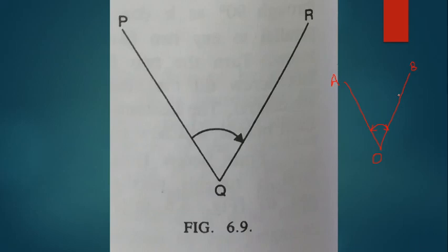Let us say it is approximately matching, then I can use the tangent screw or slow motion screw, that is the upper tangent screw or upper slow motion screw, for exact bisection of zero of vernier A with the zero of the main scale. Once it is completed, then our telescope may be pointed to any other direction which is not in line with either of the survey lines OA or OB. Then the telescope direction we have to bring onto the line OA.